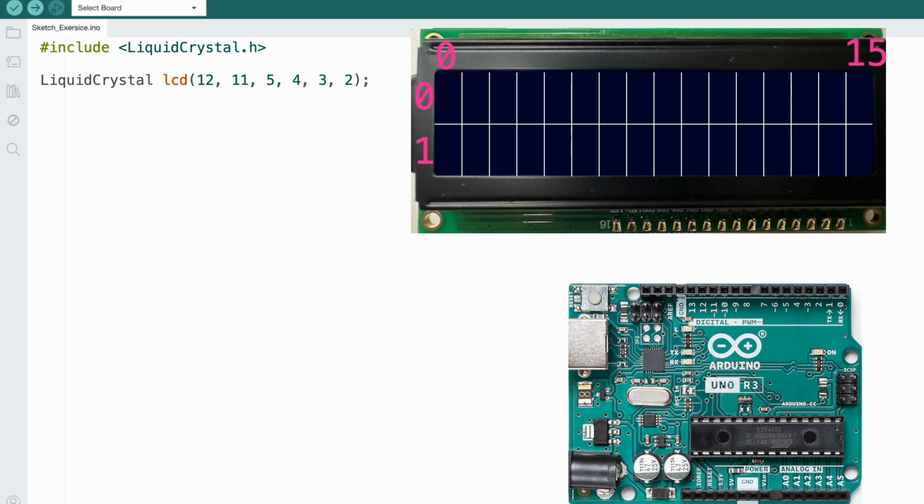Next, when we look at the 5 pin, we're going to take our output from our 5 pin on our Arduino board to the D4, which is the data line, on the LCD. Same exact thing when we're looking at our 4 pin. That's going to go out to our D5, our data line.